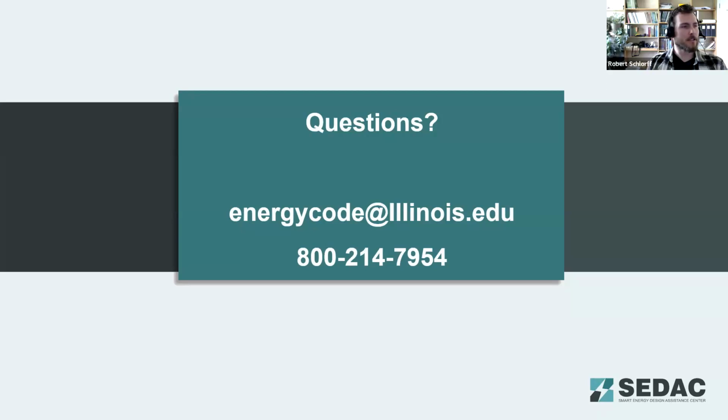I'm looking at the Q&A we got about the lighting. I think the key to your lighting question there is if that one fixture in the space is being replaced as a repair or as an alteration. If that lighting fixture is just simply being replaced as it's not functioning, that would be a repair, and then you would not need to bring the rest of the lighting in the classroom up to the current energy code. If you are actually altering that fixture and changing the output, changing the fixture type, then that could kick in having to alter the rest of the lighting in the room. If I'm understanding the question correctly there.